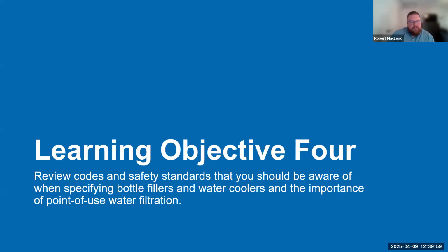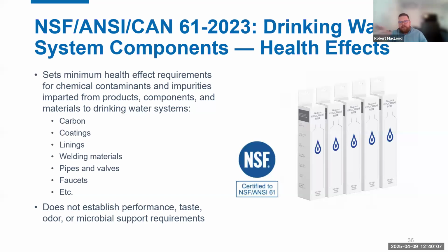Here, the last learning objective is to review the codes and standards that you should be aware of when specifying bottle fillers and water coolers, and the importance of point-of-use filtration. So beyond the barrier-free ADA standards and codes, there are codes and safety standards that you should be aware of when specifying bottle fillers and water coolers. All bottle fillers and coolers should be certified to comply with NSF 61, standard for safe water consumption.